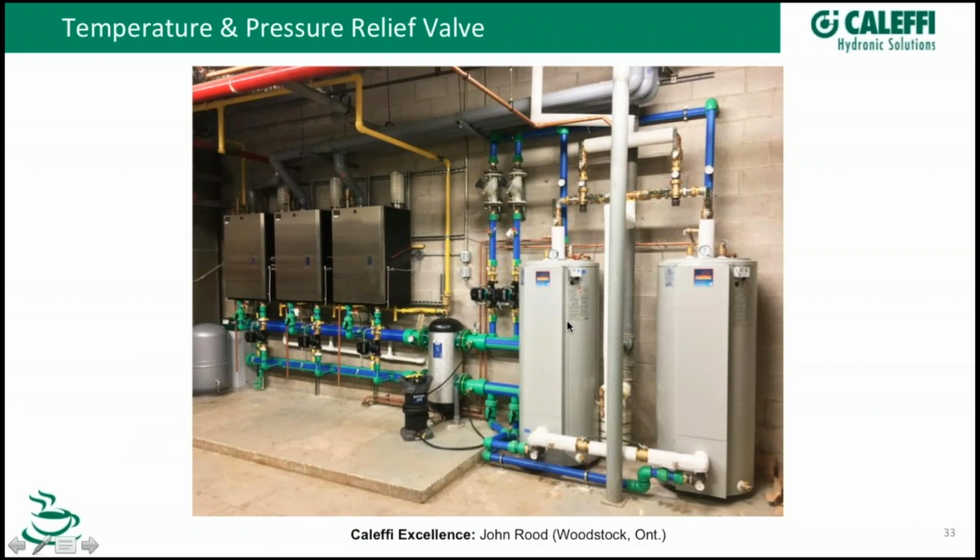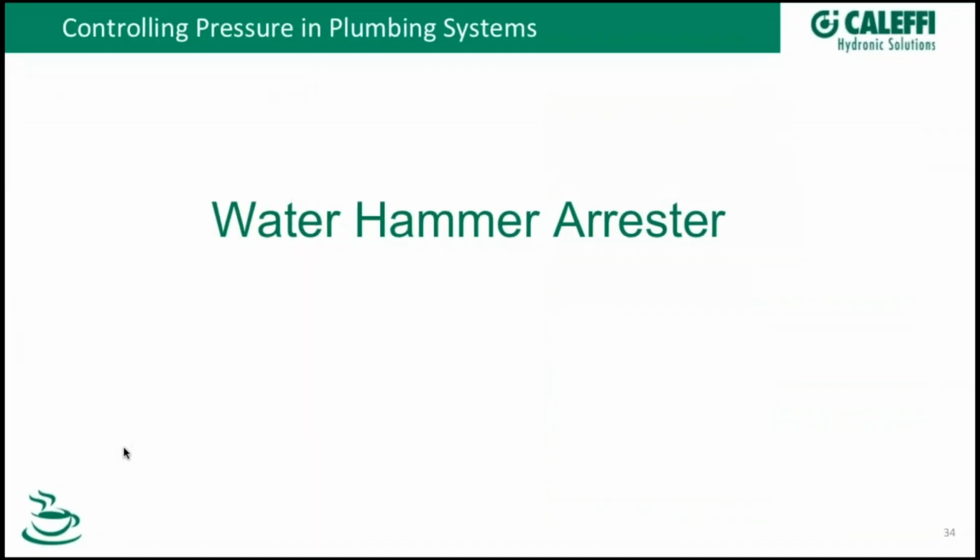So these tanks, you're going to see two relief valves on it. You'll see one relief valve that protects the pressure in the tank, typically the 30-pound relief valve like you would have on the boilers. And then up here you can see where they've cut one in on the top. That's the TMP valve that's protecting the temperature and pressure in the coils that are in the tank. So a little bit different application, but that's why you're seeing multiple valves on this tank here, because it's a reverse indirect tank. And there's the tank protection valve.